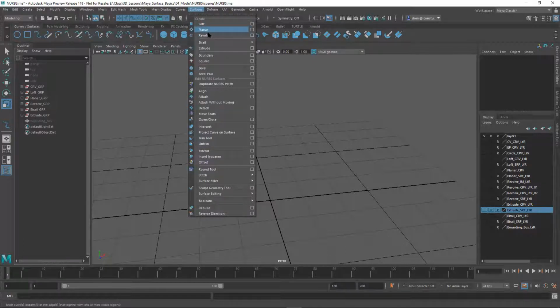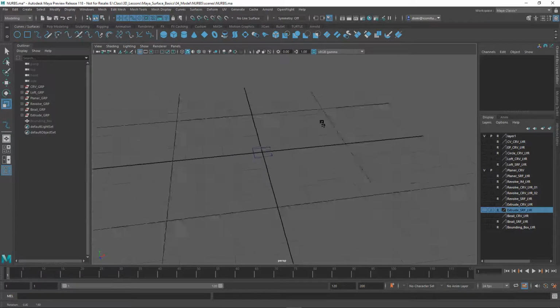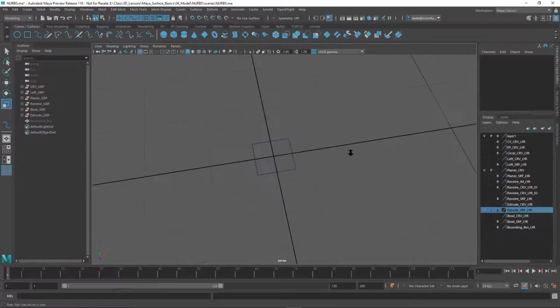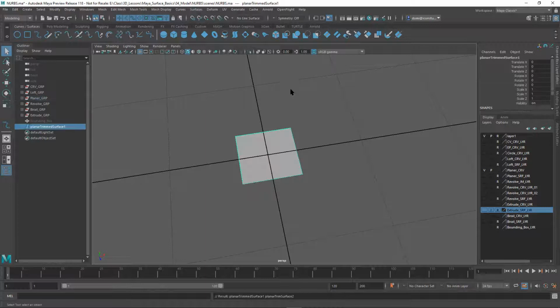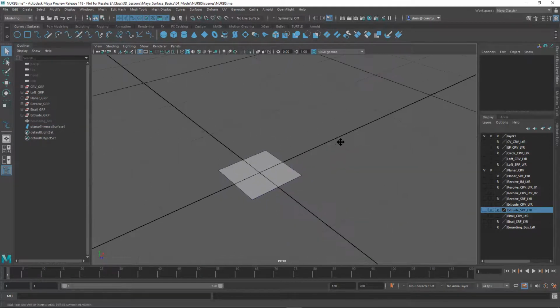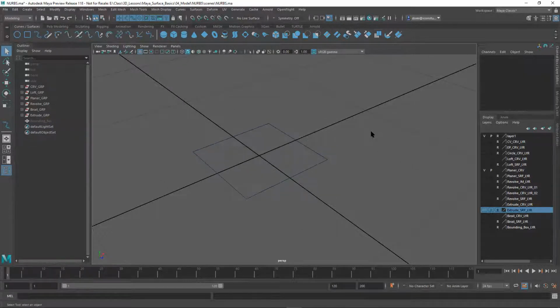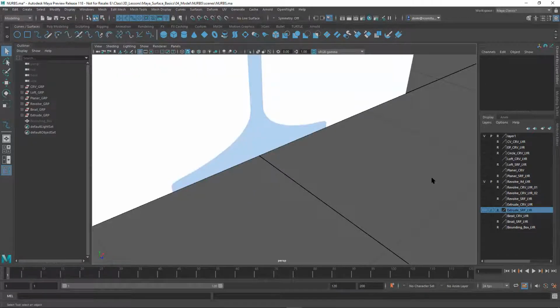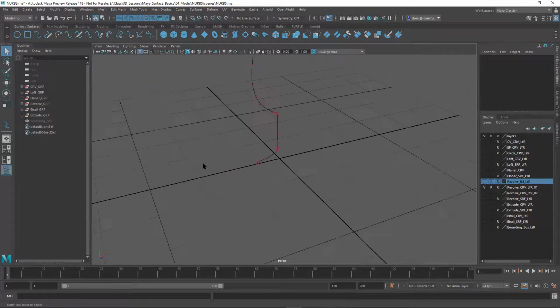Planar is pretty simple. I have 4 lines here. You just pick them, and then you go to surface. You just want to make a flat plane. That's all that happens with that one. But if you want to make a perfect plane, it's very useful. Then the next one, we've gone over Revolve. Actually, I've got the plane on, so let me turn it off first.